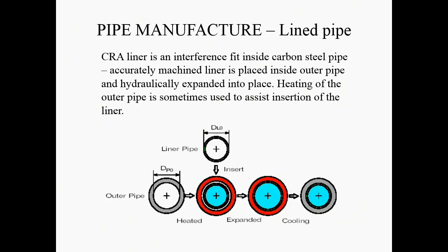And I shall finish with this slide here. One thing you can do for very short lengths of pipe is just to put a corrosion-resistant alloy liner inside the pipe. So if you've got a tube of the corrosion-resistant alloy and a tube of the pipe material, if you can slot it in, then that may be good enough. You maybe don't need to weld the two together. Maybe you can actually get that welding process to take place just by heating up or pressure expanding the inner tube until it goes onto the outside.